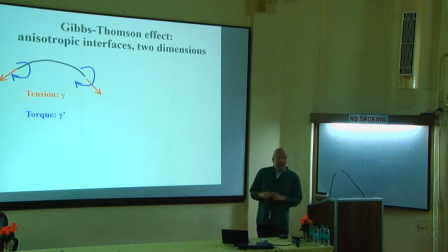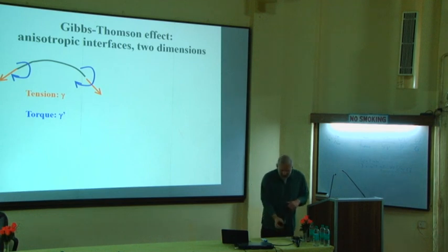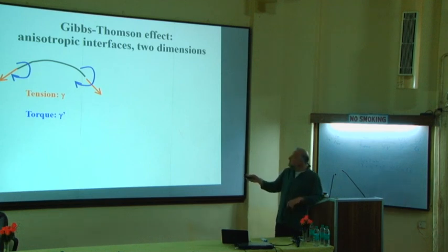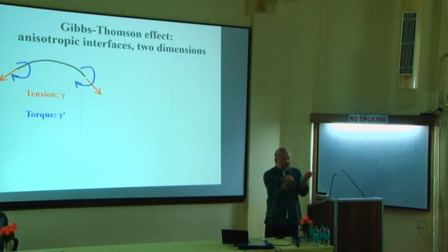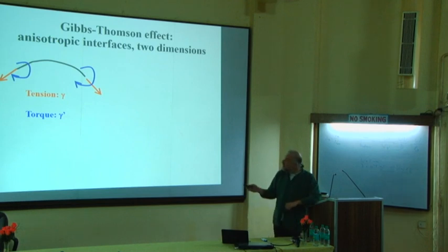So in 2 dimensions, if I draw this, these are the orange arrows. If I have a little piece of surface, the surface tension pulls on both ends. You can see that if the interface is flat, then the forces are exactly opposite and you have no net effect. But if the interface is curved like here, if I sum up these two contributions, I get a net force that goes from outside to inside. This is called the capillary pressure or the Laplace pressure. It's just proportional to gamma by r. That's the physical meaning of this quantity gamma by r that always appeared in our calculation.